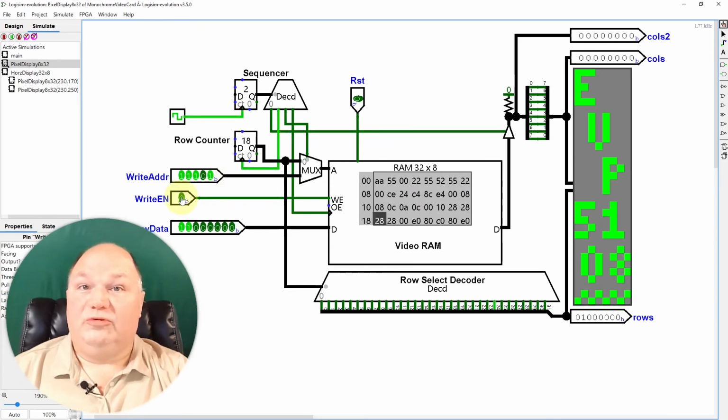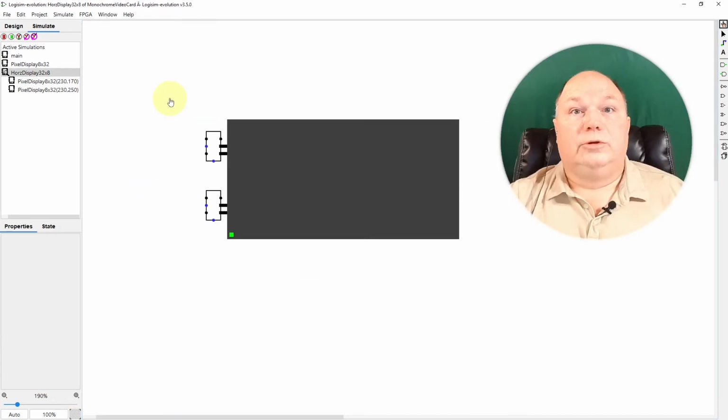And that's pretty much all there is to a basic 1 bit per pixel display such as this. As you can see, we use very little RAM using 1 bit per pixel, kind of output we can expect from a simulated microprocessor. As I mentioned previously, I have the 2 different row outputs so that I can mount the display horizontally, and we can sort of have a banded display using multiple video cards. We can expand our display to multiple sizes.